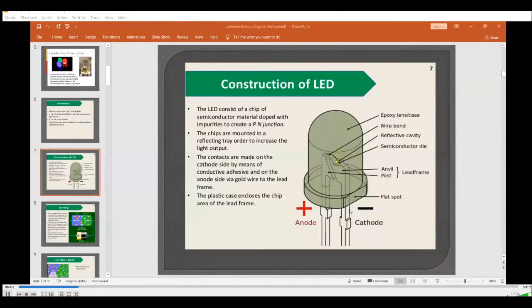So the PN junction, that junction between P and N, emits light whenever electron and hole recombination is taking place in the forward bias condition. Holes from the P type and electrons from the N type are both driven into this active region. As a result, they recombine and light is emitted. In this particular structure, we have something different. Here we are placing an LED in the form of a strip, a structured layer on a substrate.